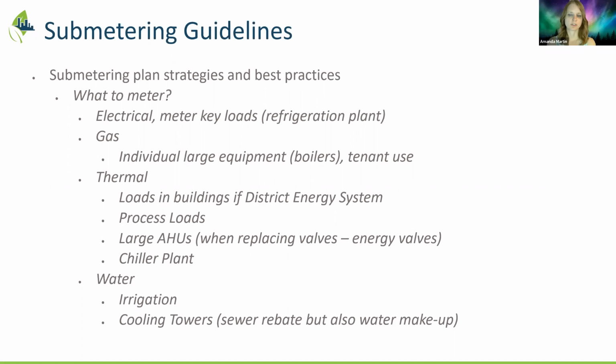We have submeters more recently on the Simcoe refrigeration plants. There's 7 meters installed with the upgrade of their system. We also have meters on our solar PV assets, 4 in total. There's several meters on the CHP, and actually your slide previously reminded me that we use the interval meter to analyze the base load and determining the size for the CHP because we wanted to run 24/7, maximizing base load.